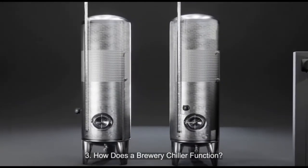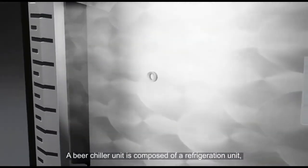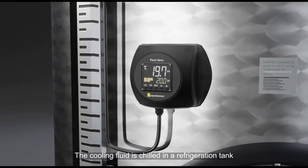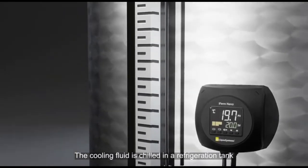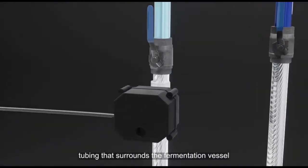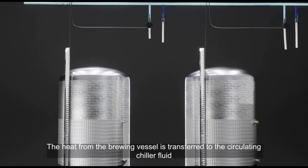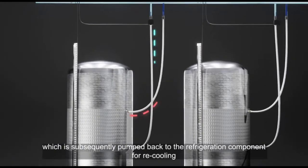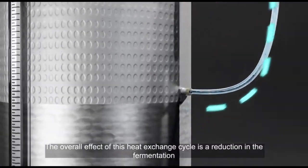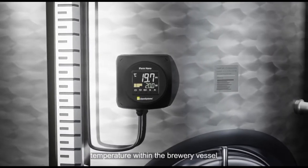3. How does a brewery chiller function? A beer chiller unit is composed of a refrigeration unit, interconnected tubing, and an automatic thermoregulator. The cooling fluid is chilled in a refrigeration tank before being pumped through heat exchanger tubing that surrounds the fermentation vessel. The heat from the brewing vessel is transferred to the circulating chiller fluid, which is subsequently pumped back to the refrigeration component for recooling. The overall effect of this heat exchange cycle is a reduction in the fermentation temperature within the brewery vessel.